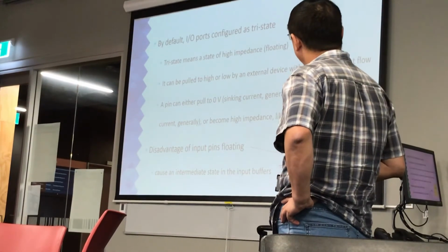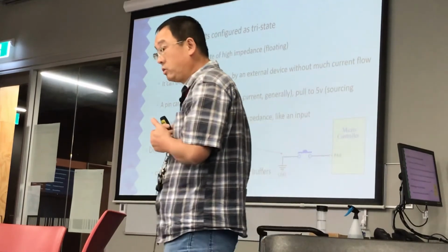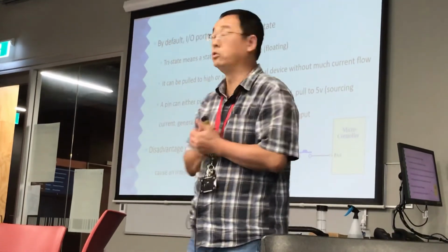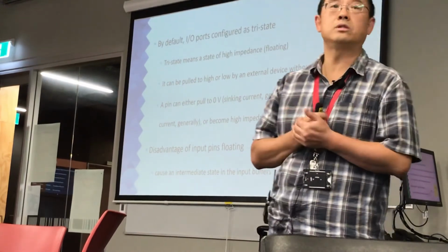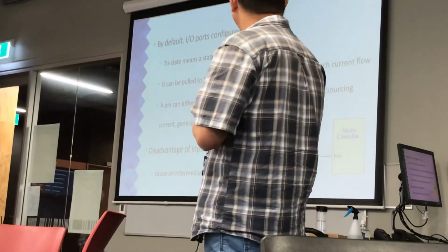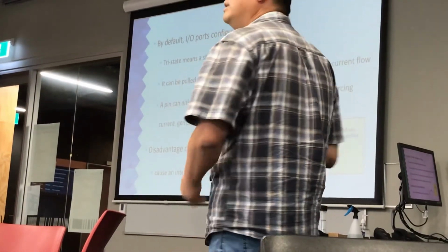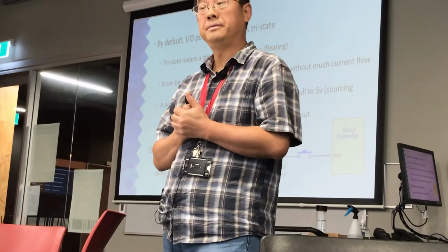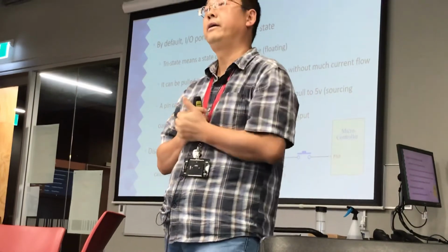Next thing, let me take a look. All the microcontroller I/O ports are configured as tri-state by default. What is tri-state? Tri-state means the I/O port is high impedance, so the resistance value is very high.